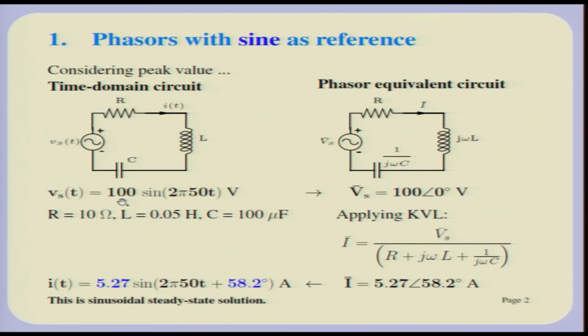Now, an important thing when you represent sine waves, remember that the source I have not only depicted by a circle with a kind of a sine wave in it in the figure there, but of course, I have also given plus or minus sign. This is just to show that Vs is the potential difference, that is the potential of the top point with respect to the bottom point. So, that plus minus means that. This is the voltage rise you can say when you go from bottom to top, and this is 100 sin omega t and is represented as a phasor.